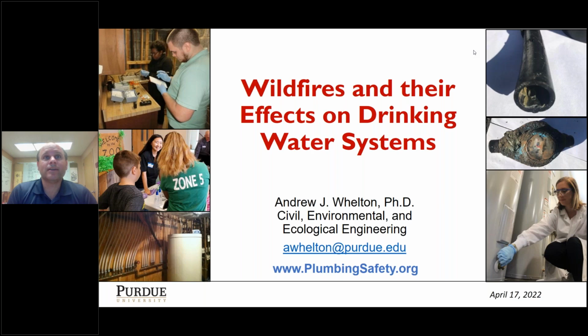I thought that this approach that I'm going to provide today is a way to bring you up to speed on what we've seen down here in the lower 48 with regards to new threats that we've just become aware of in 2017 about wildfire contaminating drinking water systems, specifically distribution systems, avoiding watershed damage, but actually contaminating the distribution system, where the treatment facilities are fine, the watershed is fine, but the structures are destroyed or damaged in the system that results in depressurization or plastics, thermal degradation, generating contamination in the system.